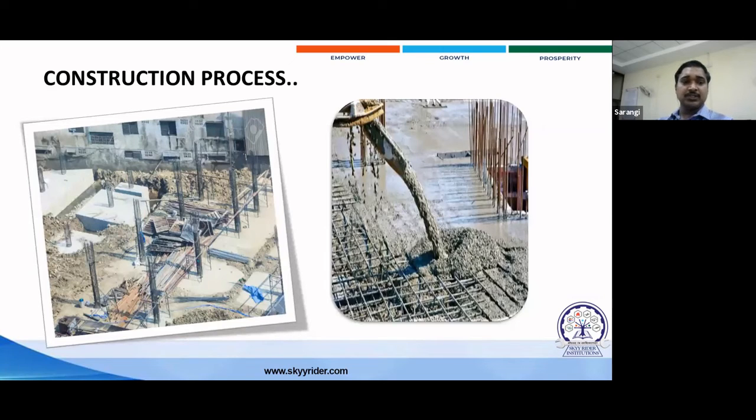In the construction process, starting from the layout of the foundations, here the footing is ready, then the column where the reinforcement, as per previously, 12 mm reinforcement is generally used, but after the modification by the building code, the minimum reinforcement for the column should be 16 mm bar. Here the concrete was poured by pumping